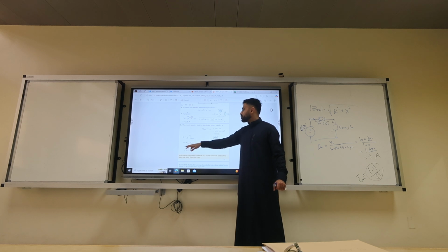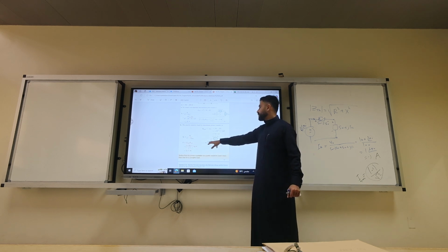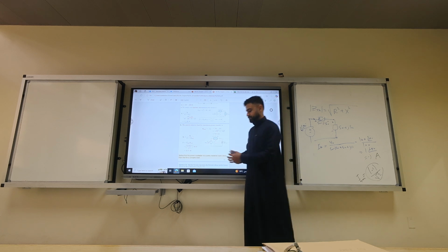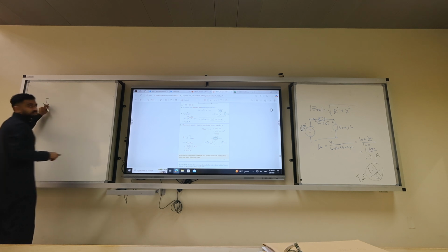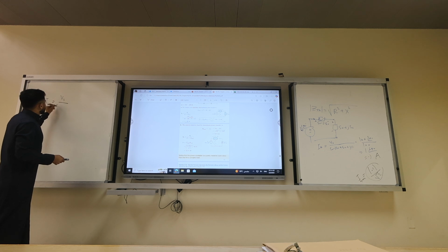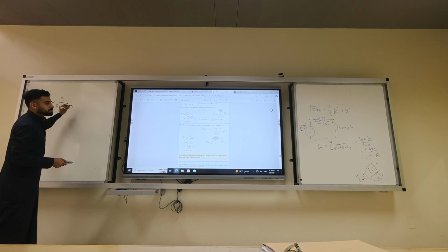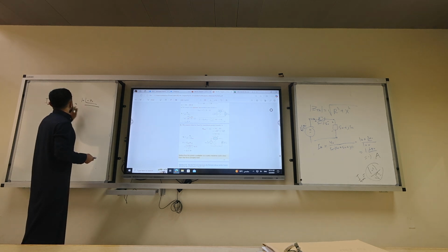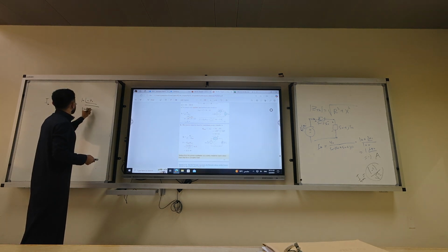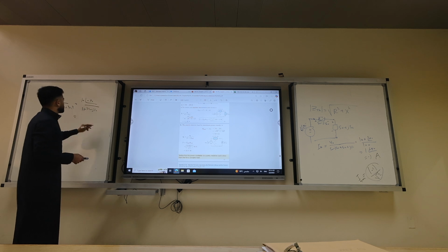So the current phasor will be, in terms of magnitude, lower. What is I B? B means part B, A means part A. V Thévenin over 50 minus j50 plus 70.71, which is 100 angle minus 90 over that number, which is 120.71 minus j50. What's the answer?